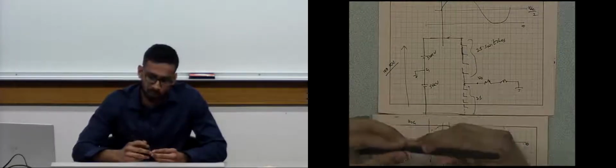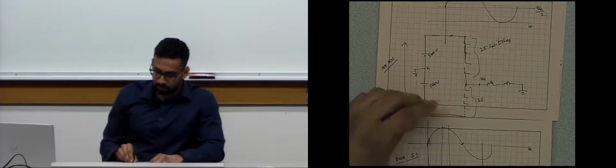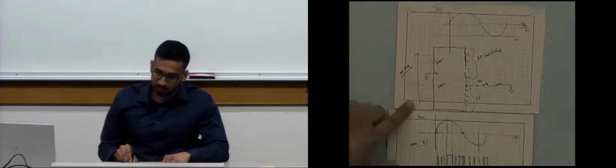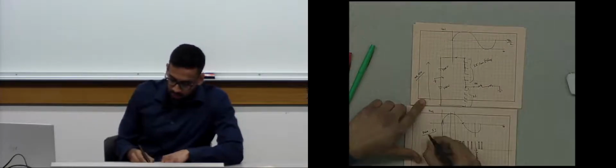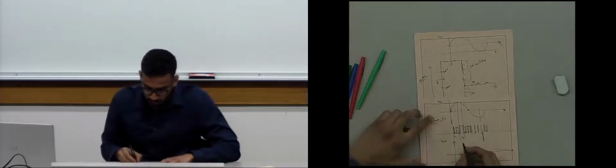And then another problem is the harmonics in the output voltage. To create VO as a sinusoid, we need to create this pulse pattern. So this is PWM S1. Let's plot VON instantaneously, not on an average basis. VON on an instantaneous basis will be just like the pulse pattern, except that the ones and zeros will be converted to VDC and 0 because it is with respect to n.